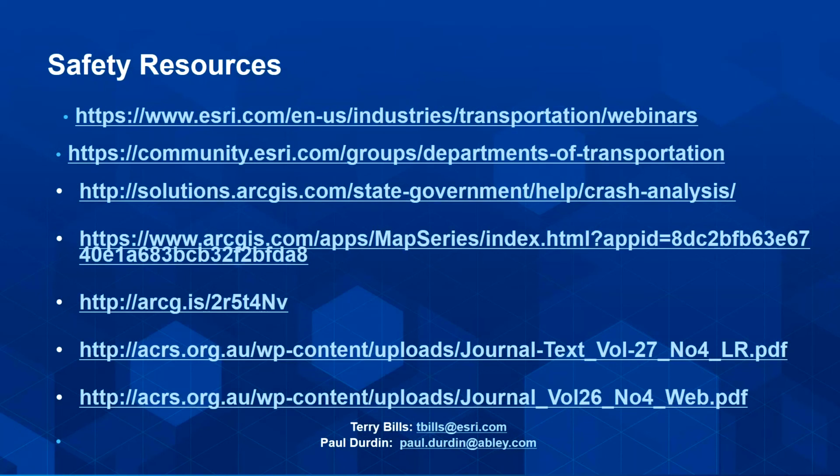to those. Whereas the new approach says these crashes indicate that if those crashes continue, much like that Glenbrook Road, Kingseat Road intersection we looked at, that if those crash trends continue in the future, we have a very high likelihood that we will see fatal or serious crash outcomes occurring, and they're the ones that we want to be prioritizing for investigation and intervention, because we remember the safe system philosophy is all about reducing high severity casualties and not necessarily about reducing crash numbers in totality.